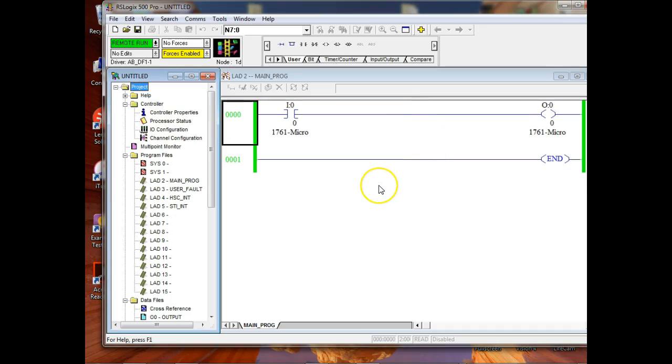And what it shows us, and we'll talk about this. So we have what we call the power rail. There's really no power. It's all logic, right? Understand that. So we make our circuits between the one on the left, which technically we call L1, and this over here is L2. The green indicates there's what? It's power. We're actually monitoring what's going on. So I'm going to come over here and press my input. And it tells me it's true.